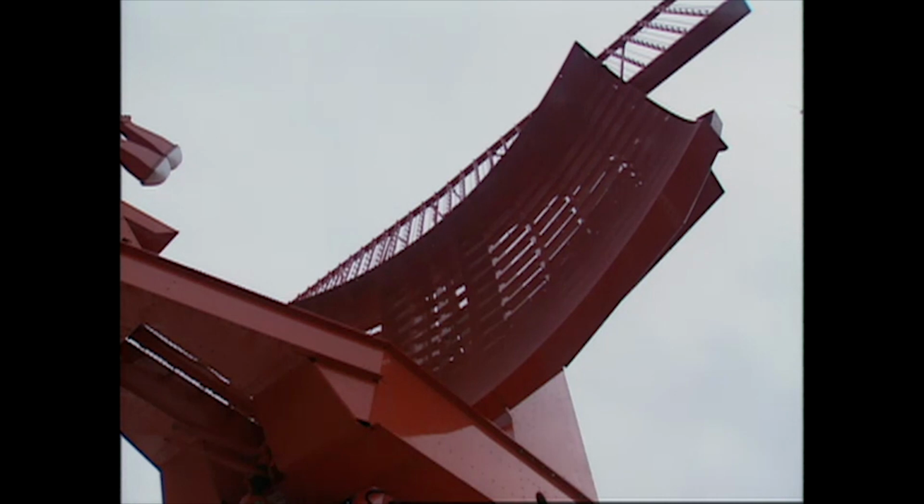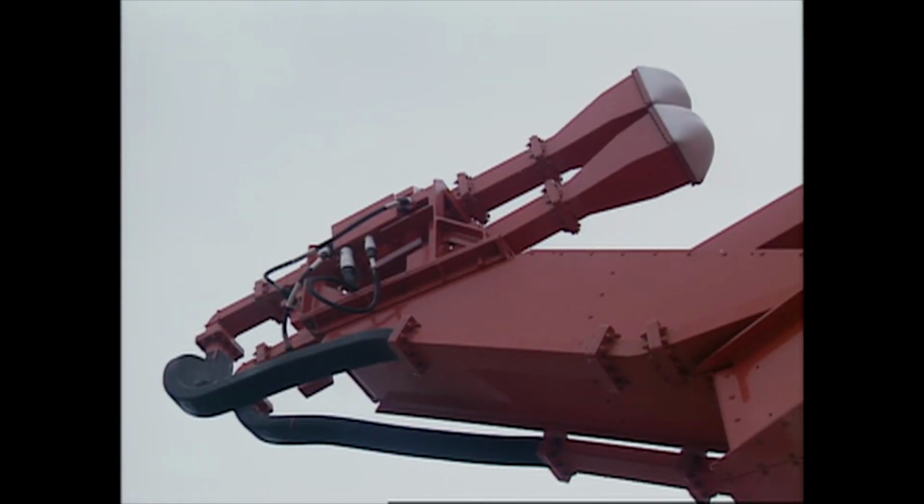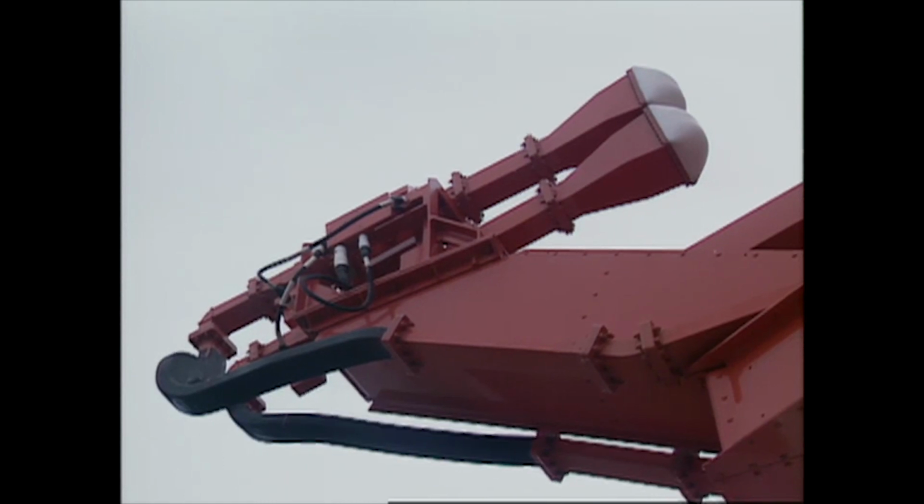Microwaves are emitted from the transmitting horn. They go out and are reflected off the parabola and focused into a relatively narrow beam at a beam width of about 1.4 degrees. Now, the antenna also works the other way too, so microwaves reflected off of targets will come back and be focused into the receive horn.